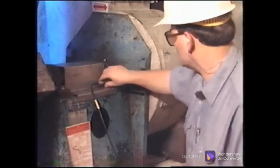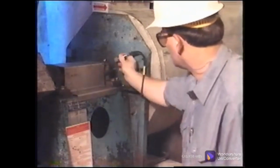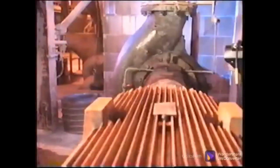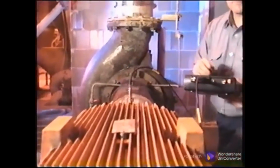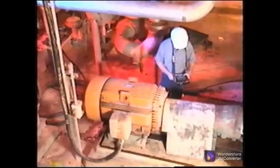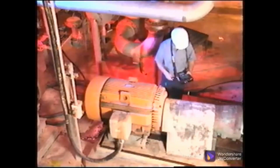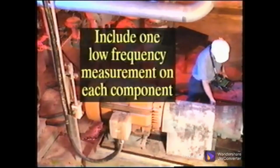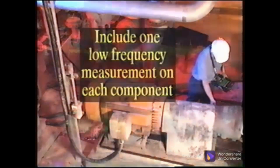In routine PDM surveys, most measurements are set to include high-frequency data to be sure to capture early stages of bearing wear and other high-frequency energy that can be so destructive to a machine. However, these measurements could be missing low-frequency occurrences that may be the root cause of the bearing failures and other high-frequency energy. Some analysts include at least one low-frequency measurement on each machine component to capture these low-frequency events.